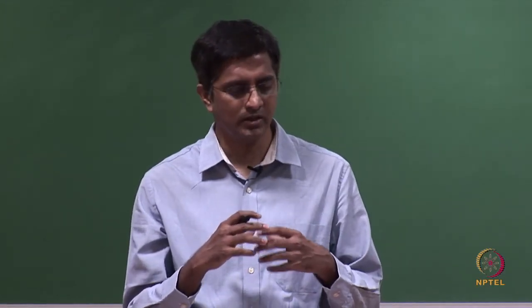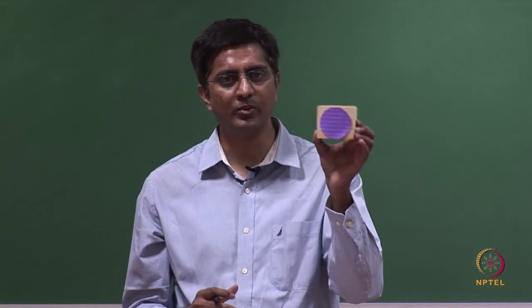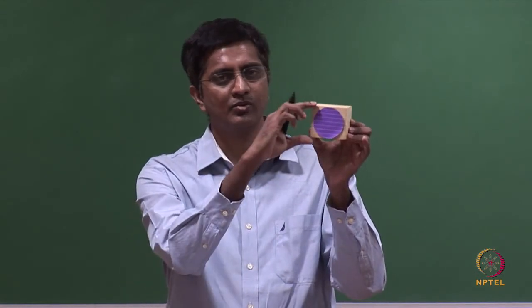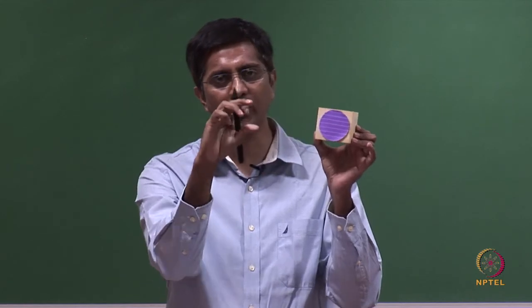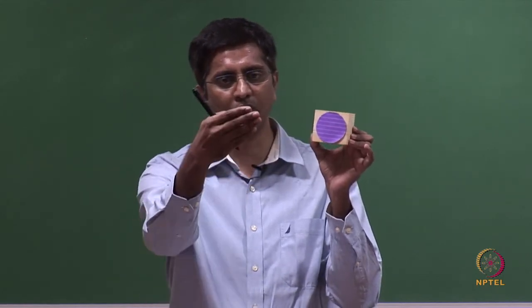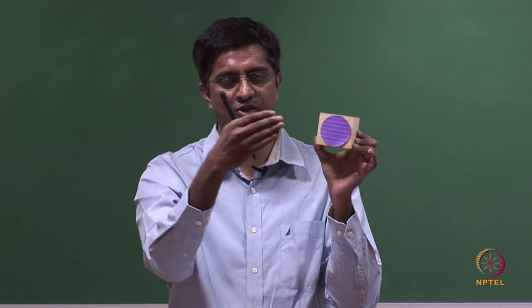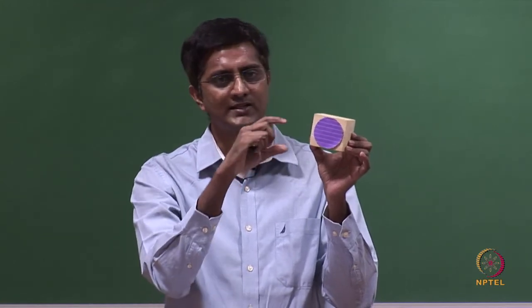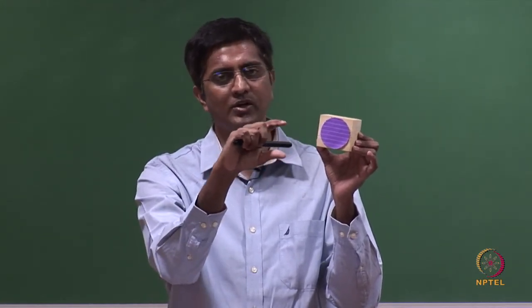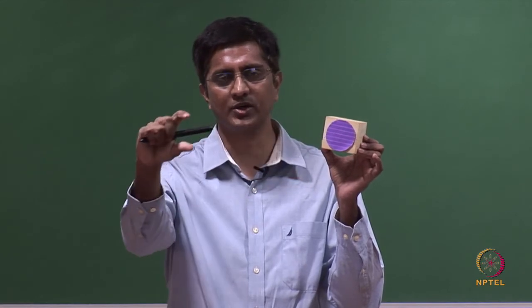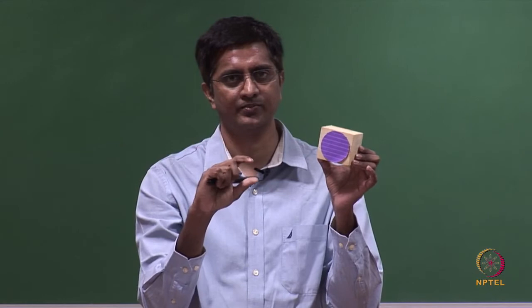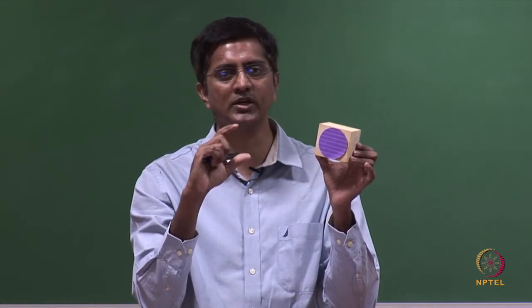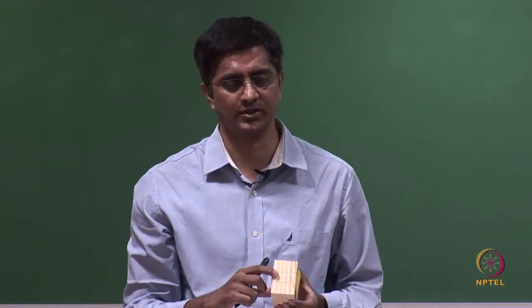It means that, let us say the size of the cube is 50 millimeters, but when you draw it on the projection plane, depending on how far or close your projection plane is, the size of the cube that you draw there might be 40 millimeters or 30 millimeters, which means you are not looking at the true length. So, you are distorting the dimensions of the object.